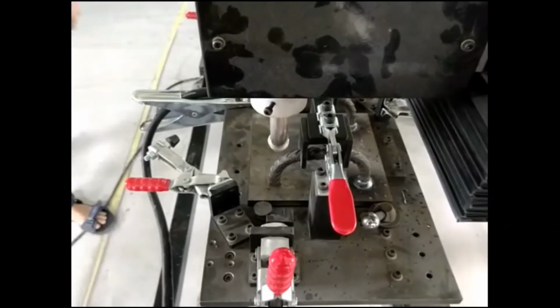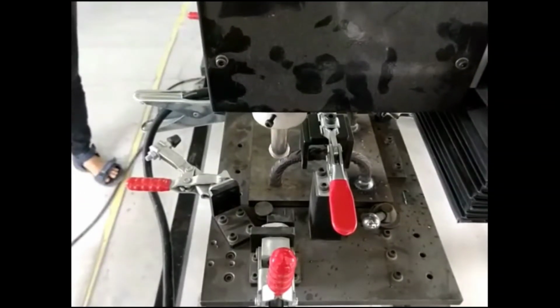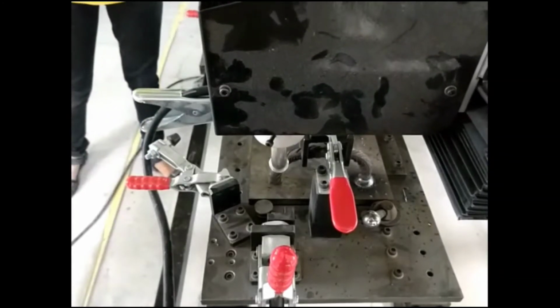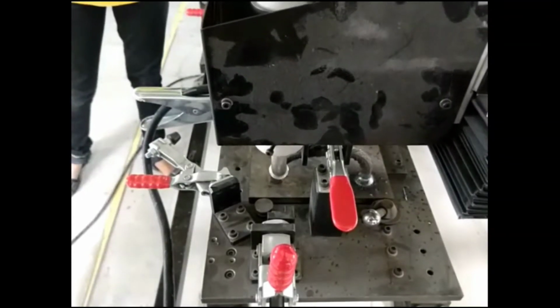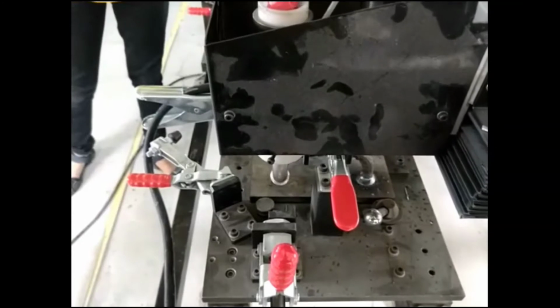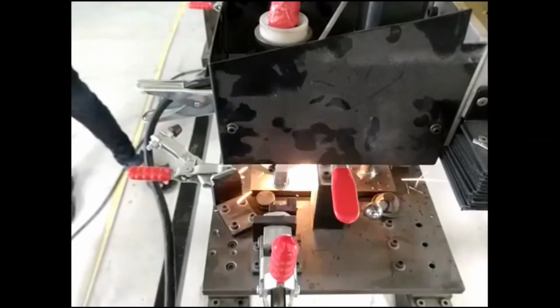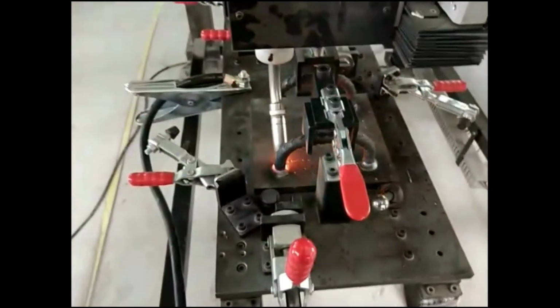There are about 4 plus 1, 5 circular profiles. You can set it automatically, it's based on our teach functionality, and once you set it, you just have to start the program. There are about 10 programs here, so 10 variations that you can weld. In case you want to increase the number of programs, you can do it by extending through a USB dongle or a thumb drive.